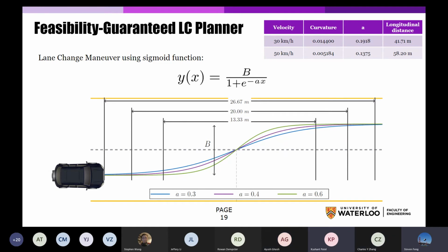Yeah. So we tried to integrate our Frenet planner with a PID controller at first. There was much noise when we were trying to calculate cross-track error and trying to minimize the error. And we noticed some lateral deviations as well. So we switched to using a PID controller with a feed-forward controller. But again, we were facing problems there as well.